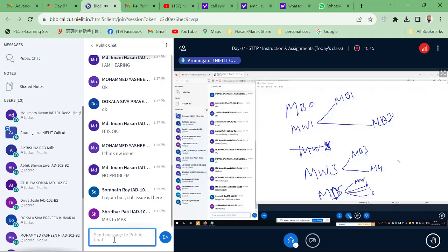You must follow these rules for the 300 and 400 series controllers if you are using Step 7. That is mandatory. Otherwise, sometimes you will get garbage values. Actually, the PLC will be working, but you are not able to get the correct data. So be very careful.